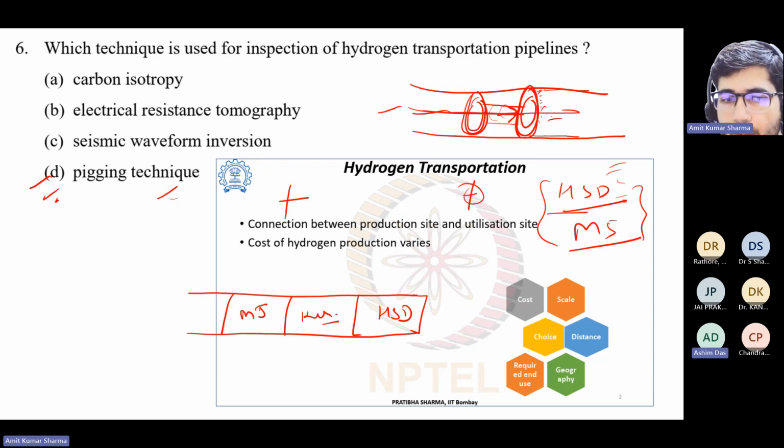Now you need to calculate how much kerosene you will need. It will be based on the length of the pipeline and the flow rate. They have some calculation for it. They calculate how much kerosene to push so that this interface will not be that large, and we can have pure kerosene in between, and the diesel and petrol will not mix together. So this is how it works.